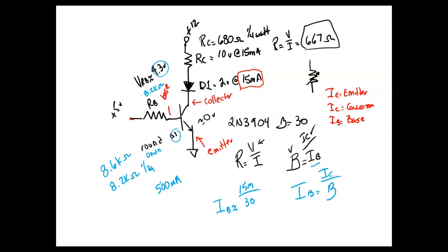but what happens is we're dealing with Kirchhoff's law. I know there's a p-n junction right here. If you can look at this, there's a p-n junction right there. And this is for silicon, right? Now they do have germanium transistors, by the way. If it's germanium, we use 0.3, but the 2N3904 uses silicon.